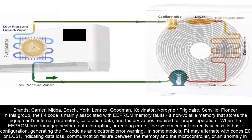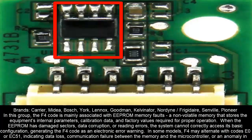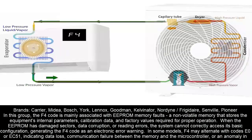In this group, the F4 code is mainly associated with EEPROM memory faults, a non-volatile memory that stores the equipment's internal parameters, calibration data, and factory values required for proper operation. When the EEPROM has damaged sectors, data corruption, or reading errors, the system cannot correctly access its basic configuration, generating the F4 code as an electronic error warning.